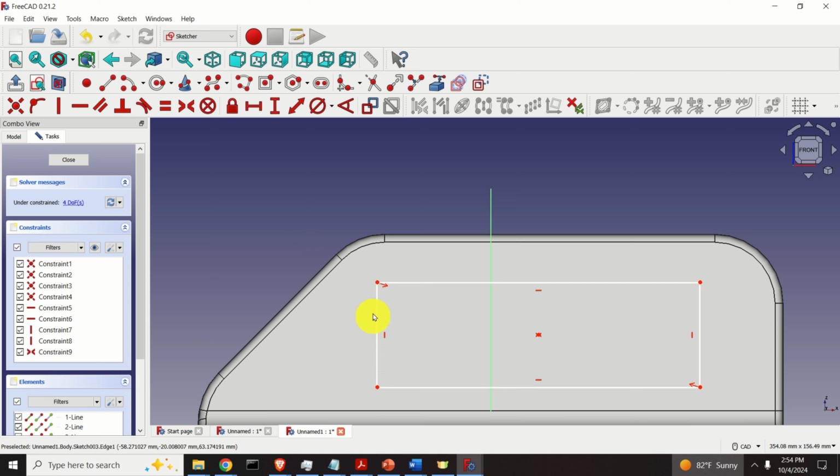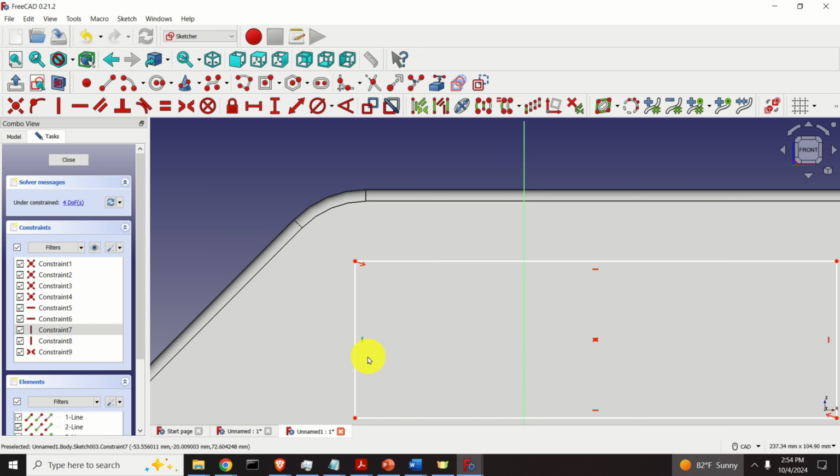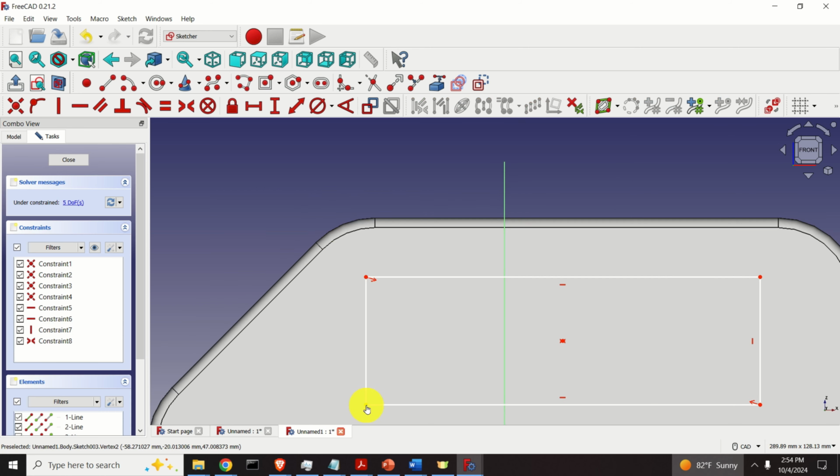Now, I want this edge of the rectangle or this side to be parallel with this surface over here. Let's learn how to do that. First of all, click here and let me zoom in to show you. You need to click on this small line over here. Let me again show you. Here it is, and delete. Now you erase the constraint and you can independently move this point from the point over here. And let's move it somewhere here.